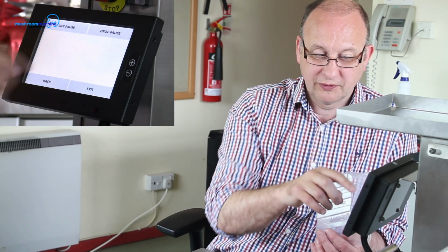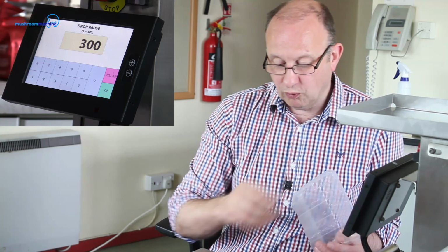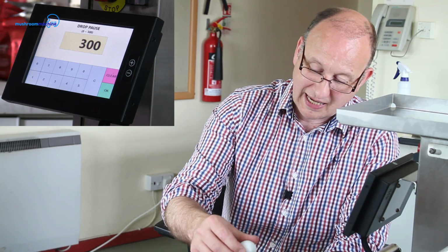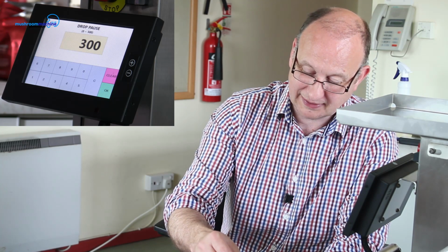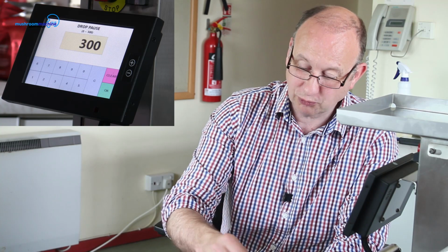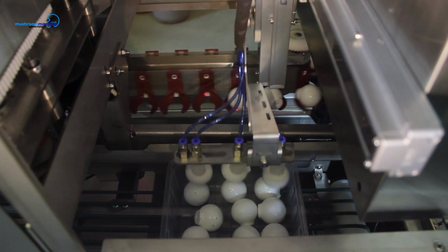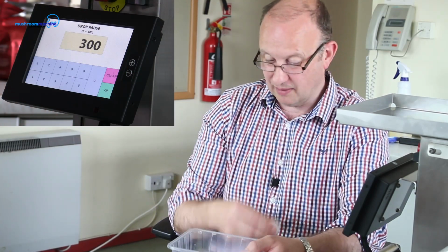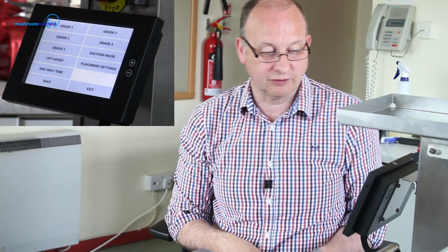Now this was one that I had to change on site. We had a drop pause. What we were finding was when the mushroom went over, if it was a button mushroom and very light, when we released the vacuum, it was like sitting there on the suckers. So what we had to do is change the drop pause, move it a wee bit longer, and actually drop down into the punnet. Whereas before it was coming on its way back before it dropped, or maybe even past it. So simple things like that make a fantastic difference to what you're trying to do.